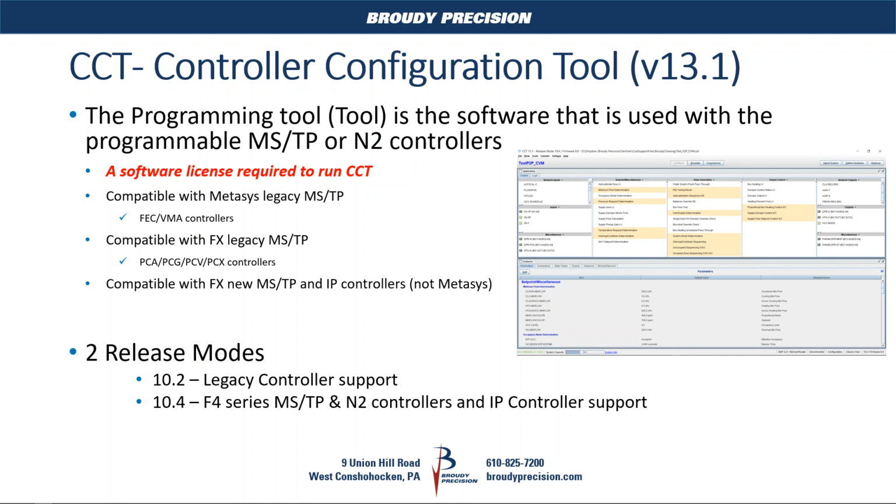That's something you couldn't do with PCT. You had to have the Metasys version of CCT, the older version, to run Metasys product, and you needed the PCT tool for the FX product. So with CCT 13 running 10.2, you can work with the Metasys controllers or the FX controllers.